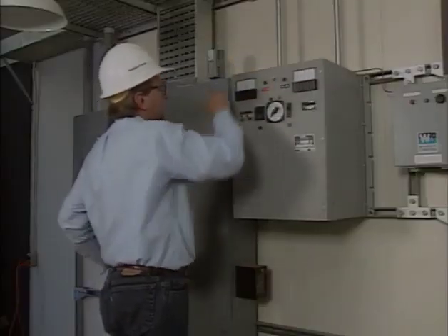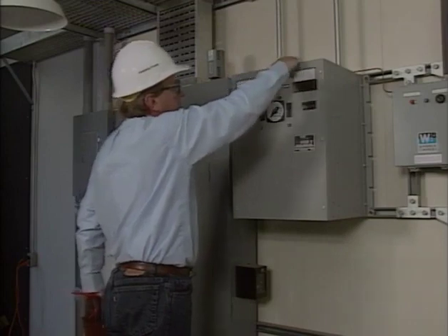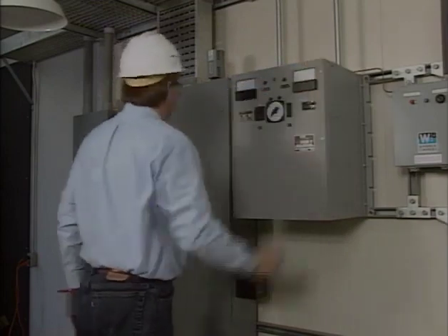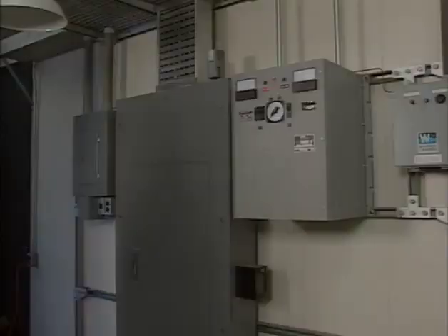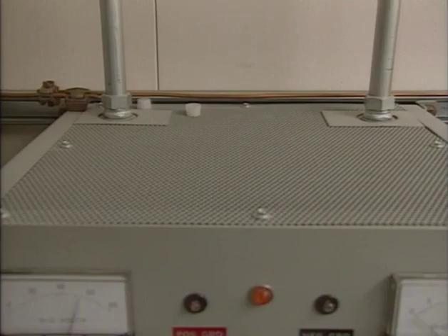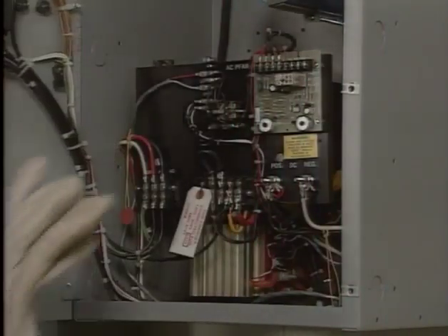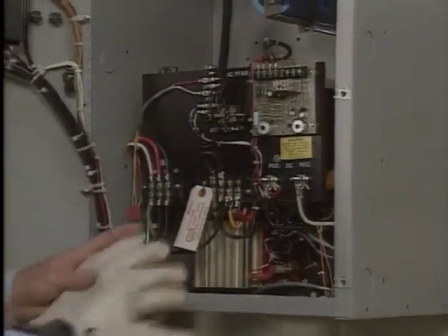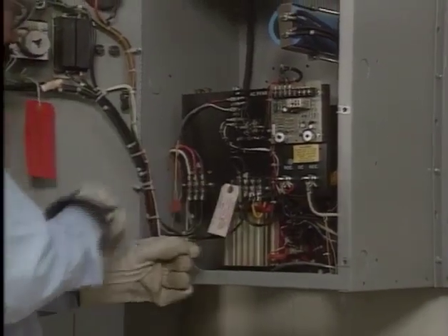To ensure good ventilation, the area around the charger should be kept clear so that nothing interferes with the free flow of air. In particular, the ventilation openings in the charger cabinet should be checked for obstructions. The interior of the charger is also checked for signs of heat, such as discolored terminals.